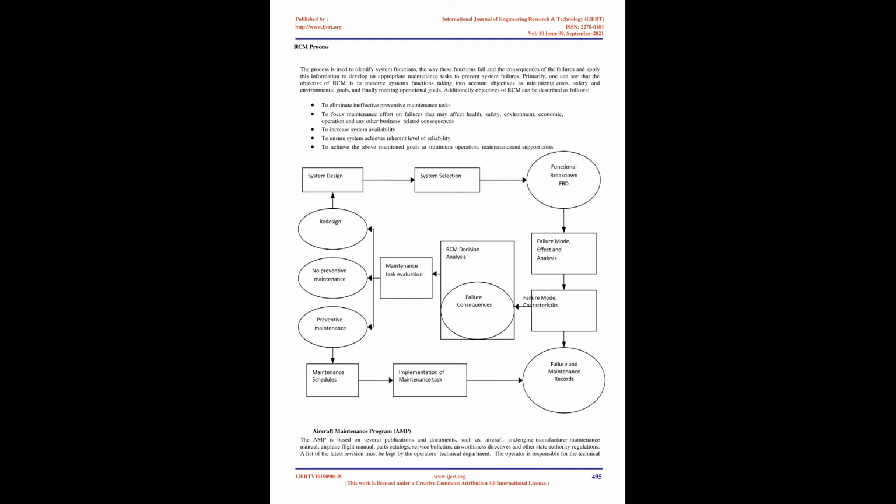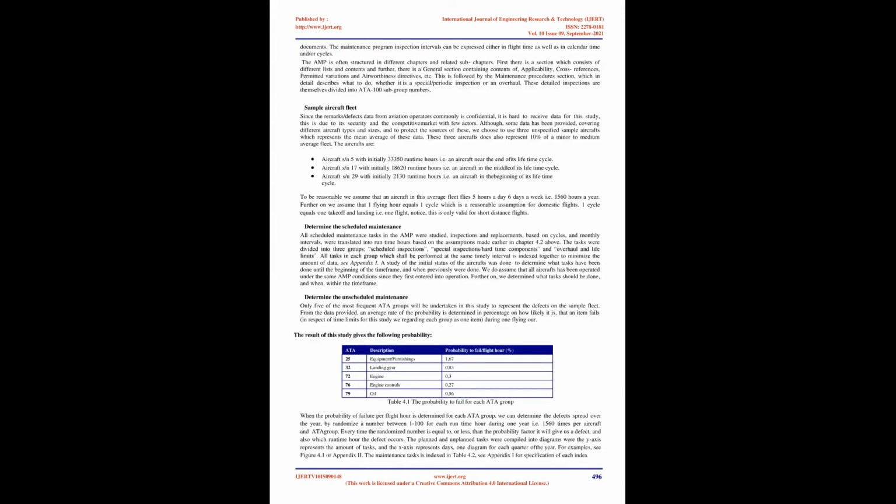The RCM study has established that there were 6 failure-related patterns. The most common failure patterns show a failure rate decreasing with age before going into a period of random failure pattern, and the most uncommon patterns show a failure rate which is constant with age before going into a period of increasing failure rate. See all 6 kinds of patterns established in the figure.